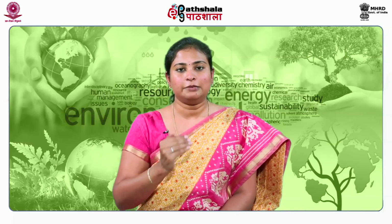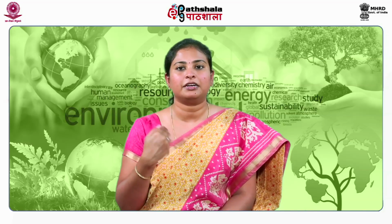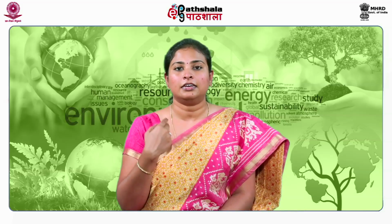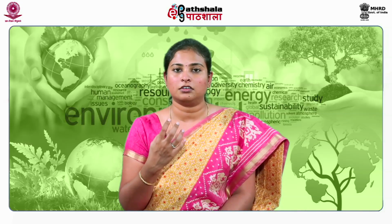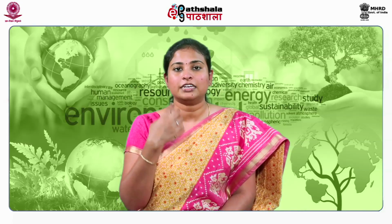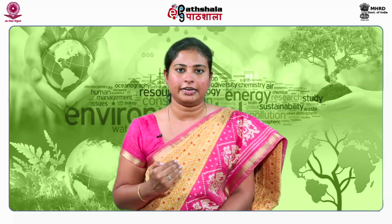This component helps in assessing leachate or gas leakage, if any, and environmental contamination. That means if you continuously monitor for any gas leakage, or continuously assess the leachate characteristics, you can judge what process is happening inside the landfill bioreactor.